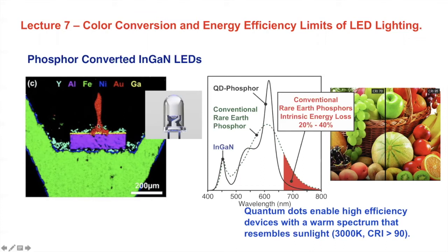And so the blue light photoexcites this powder that produces the other colors of the visible spectrum, and it gives you a photoluminescent spectrum like the one shown here in the dashed green line. There's the blue peak from the indium gallium nitride crystal that's doing the work. And then this broad dashed line is the luminescence from cerium, which is doped into yttrium oxide and spans the visible.